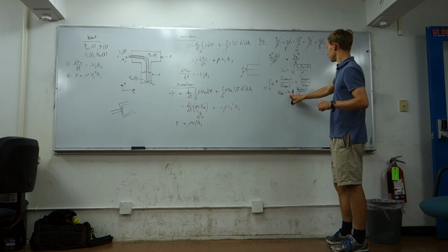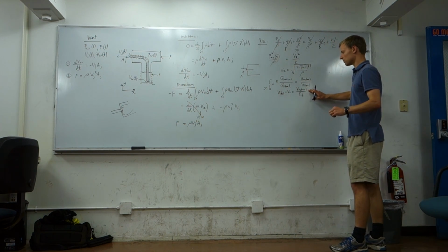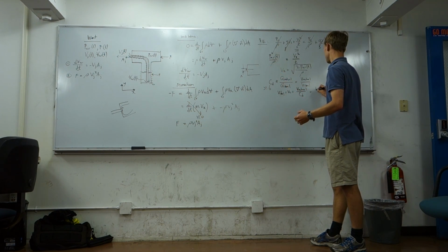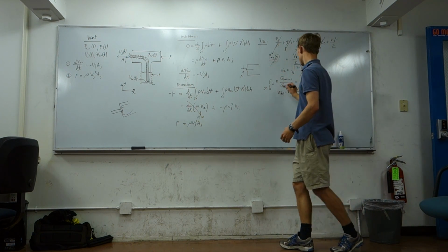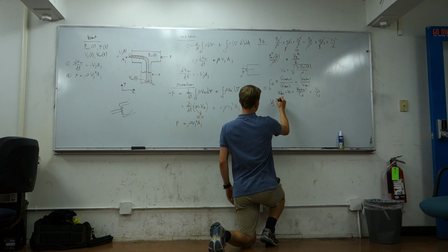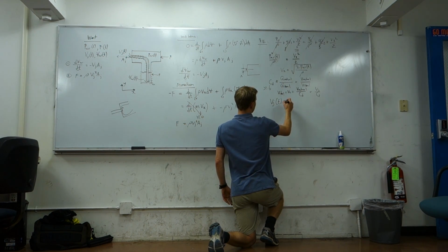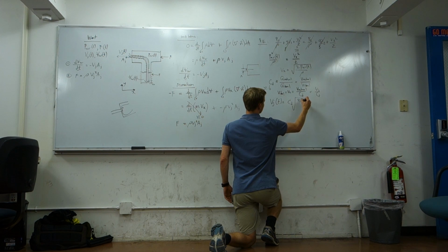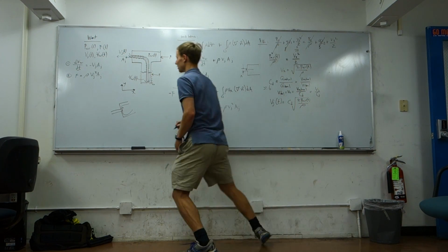So we know that V2 is up here, and V actual is the actual velocity of what's coming out of the nozzle, which in our case is Vj. So this is Vj over Cd. So we're left with Vj, as a function of time, is C sub D times the square root of 2 P air over rho. That's our third equation.